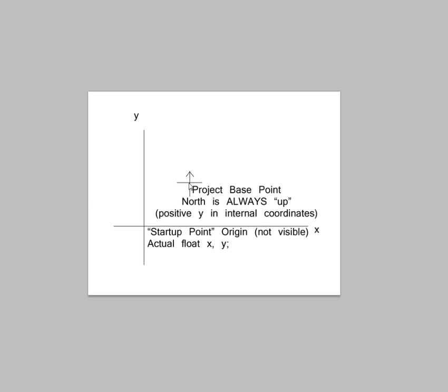Okay, so now let's move on to the project coordinate system. Really, this is just a point that is a reference mark internal to any given file. It isn't shared between files. It's just used as a reference for spot coordinate annotations that would be useful to the builder. And I'll give an example when we actually go on to Revit in just a minute or two.